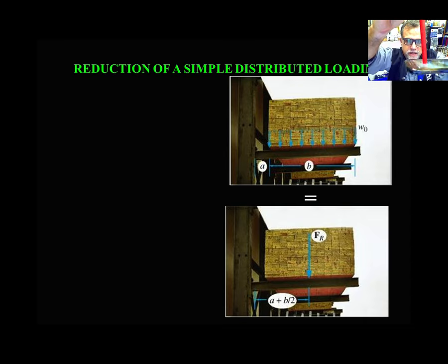So if I put this thing here, and you have to represent this force on top of the cell phone, you put an arrow, because that's what you do. And that's okay, and that's a concentrated load. However, if you look at the tip of this pen, the tip is not a point. There is a surface here. So whatever force I am applying from the top is getting distributed along this area. In the majority of cases like this, you assume that area is small, so you consider that the whole force is applied at that point. You can do that, yes, but usually it's not the case.